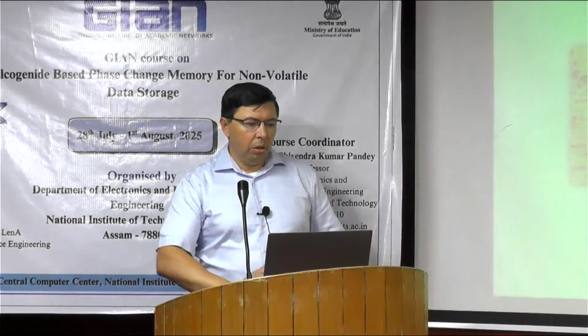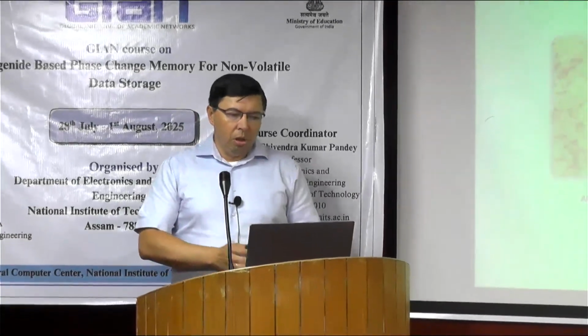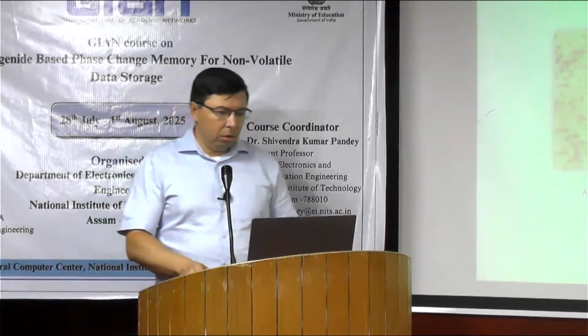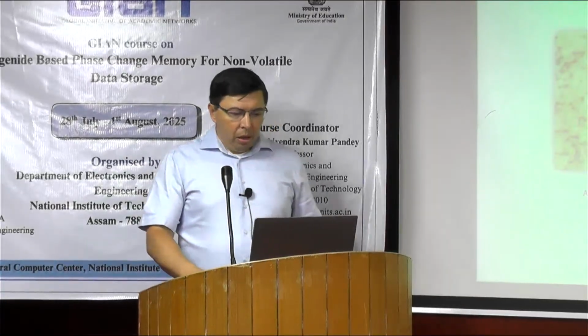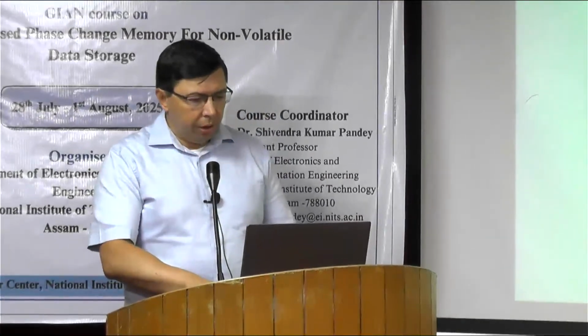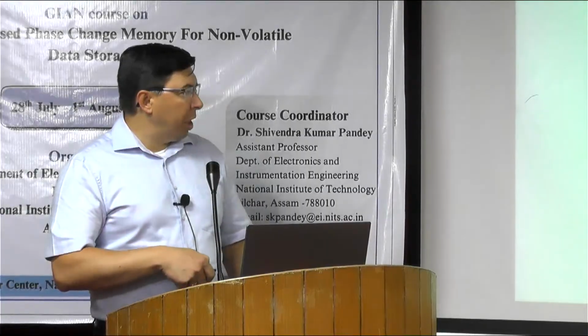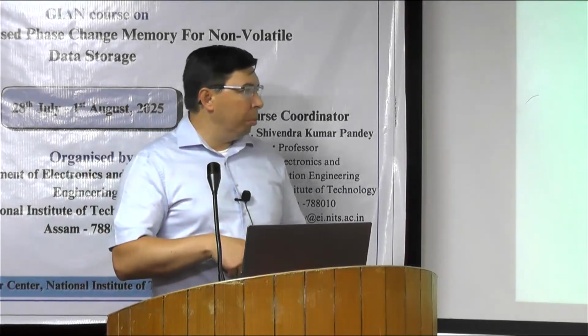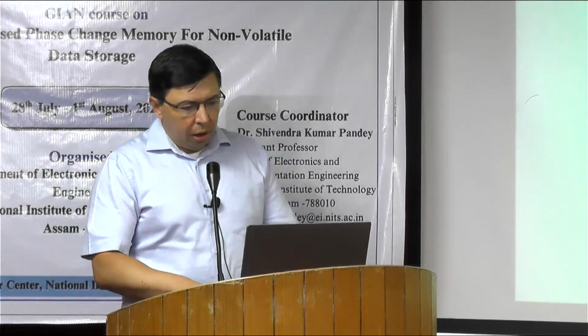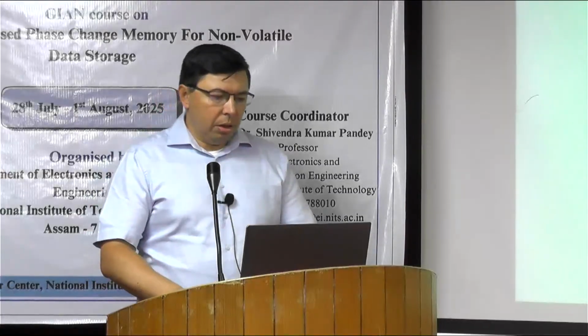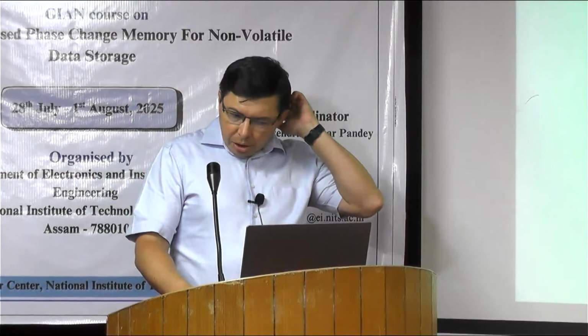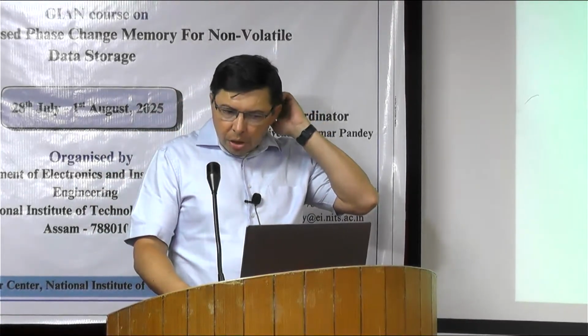Now we can continue our tutorial on TEM. So here there are some troubles with mechanical thinning, mechanical polishing. What can happen depends on your material, if it's hard or soft.